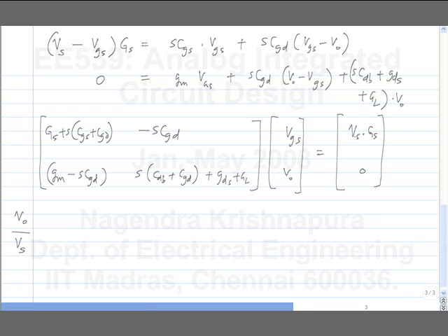So Vs is the input, or we can call it Vi. Okay, let me call it Vi instead. So what is V0 by Vi? What is the DC gain? What will be the DC gain of the circuit? Gm by GDS plus GL.